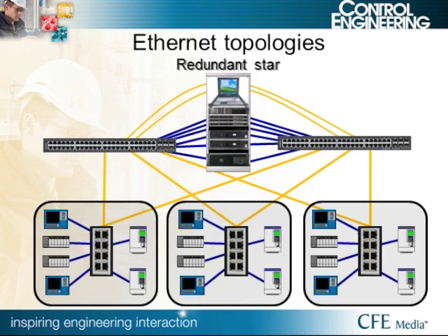Then you can add more media connections between the switches and use the multiple network interface cards on the servers to connect each of them to a different switch. This example uses fiber for the redundant switch connections, but you can use copper without affecting the heal time. In essence, you are creating multiple rings between the switches in case one of those 48-port switches in the server rack fails. This is great for process systems where a controls failure in the middle of the process might ruin the whole batch.